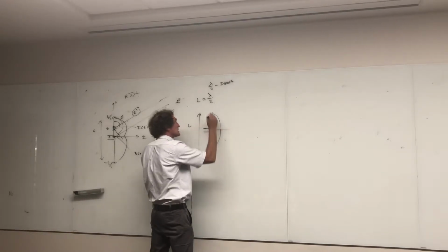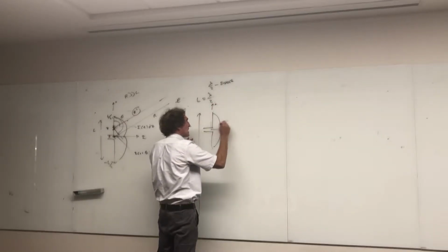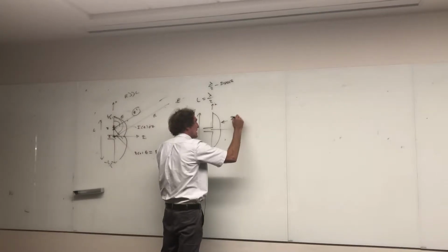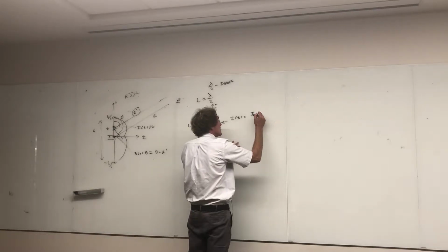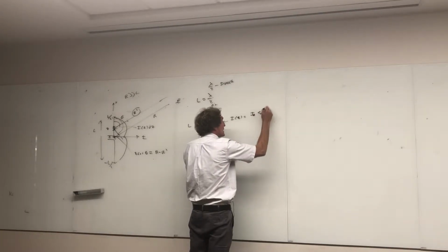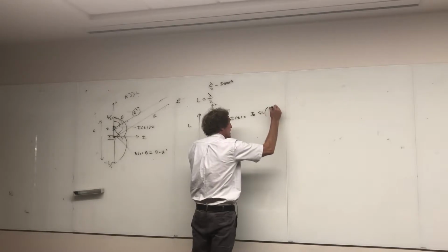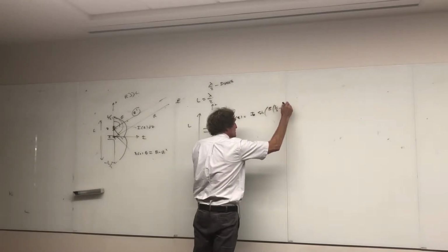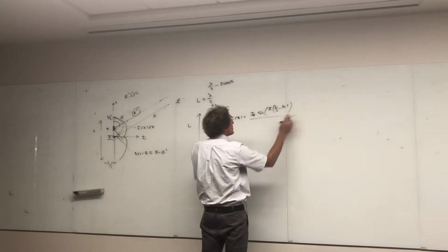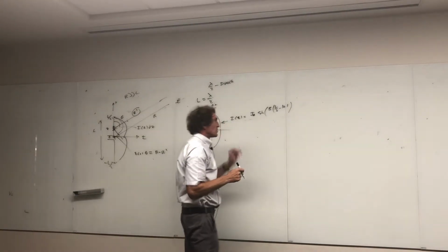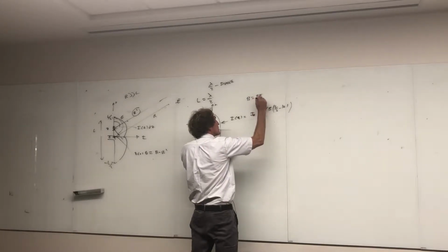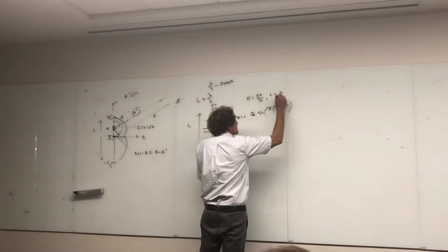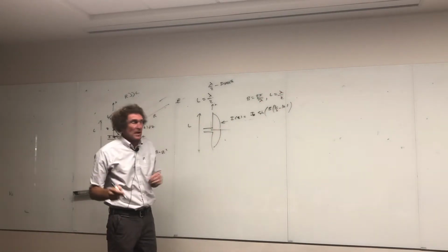If this is the z direction, I of z is the interesting thing. If it's a half wavelength, it's I naught times the sine of beta times L over 2 minus the magnitude of z. Well, that's the current there. Beta is equal to 2 pi over lambda, and L is lambda over 2. That's all you have to know.